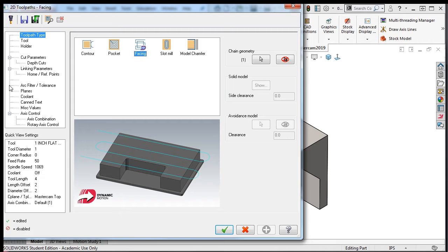This part is being machined from a mild steel weldment. The overall plate thickness is not important, but the squareness of the two faces is. So the purpose of the face milling toolpath is to take a light cut off of the part and remove any warpage from the welding process.